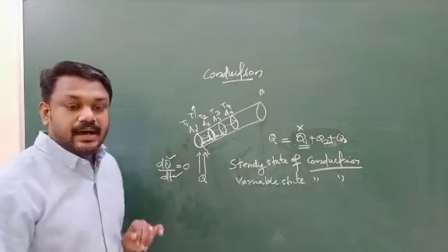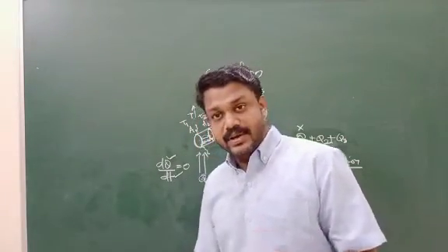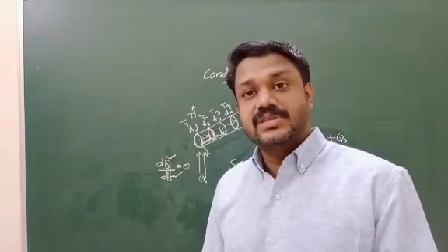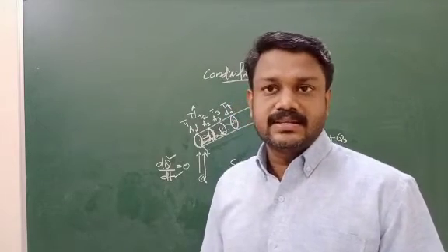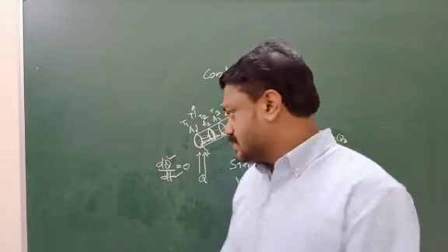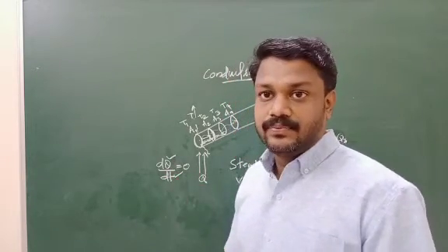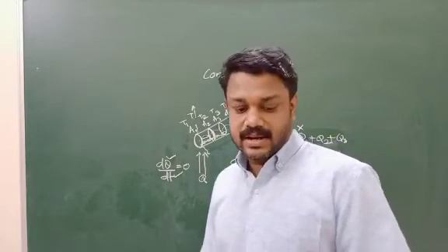That means when you are supplying heat into the situations in different cross sections, its temperature will not change with respect to time. That means it is not absorbing any amount of energy. That is why its temperature remains constant. So d theta by dt will become 0 at the steady state of conduction.